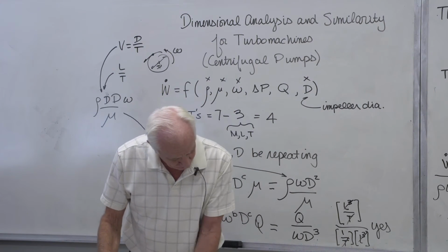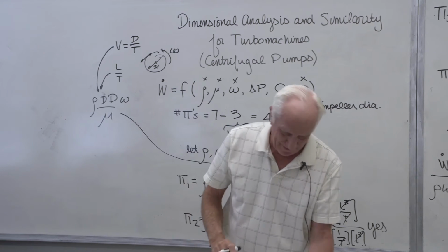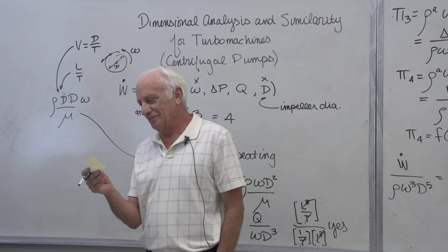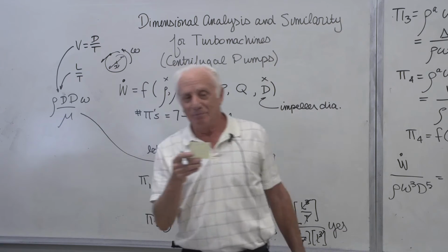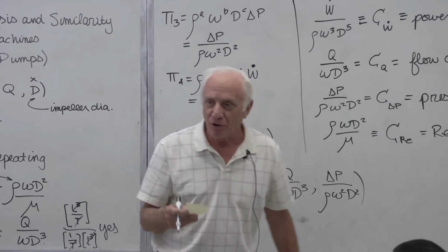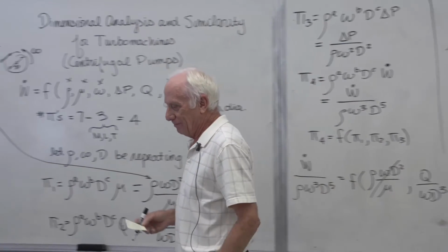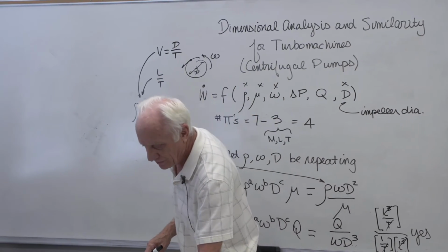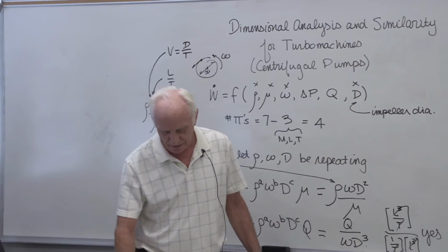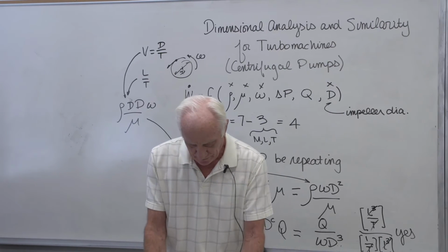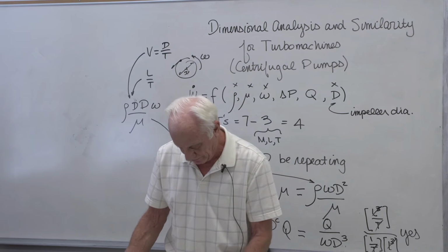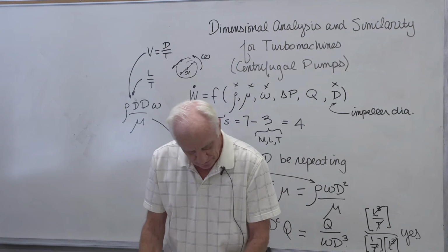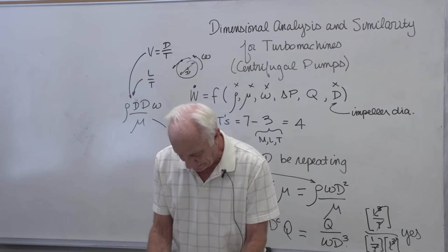Also in a pump, it's turbulent flow, there's blade roughness, there's eddy formations, the spinning impeller creates eddies, there's flow separation, a ton of stuff going on. So we don't think the Reynolds number plays an important role in pump analysis. Pipes, for sure.